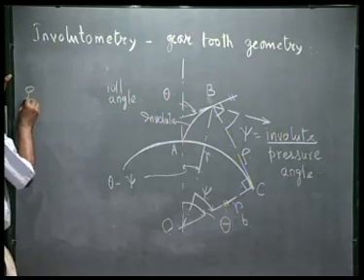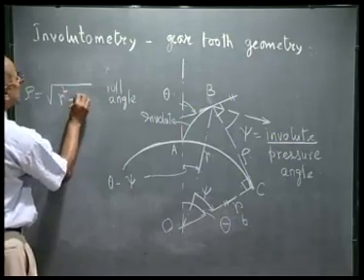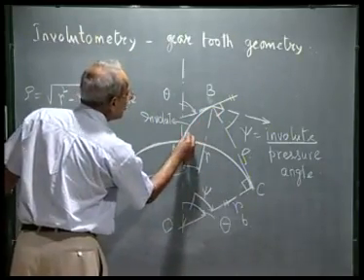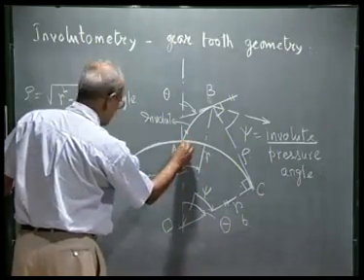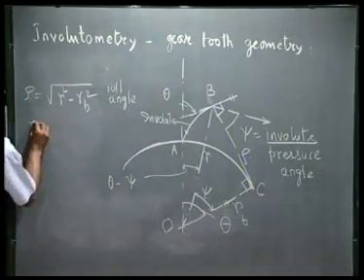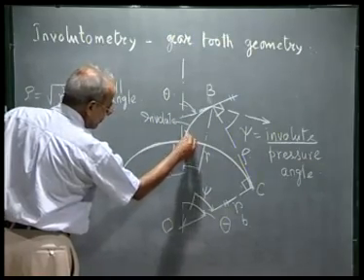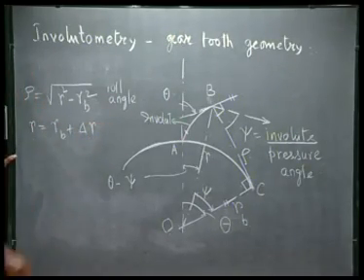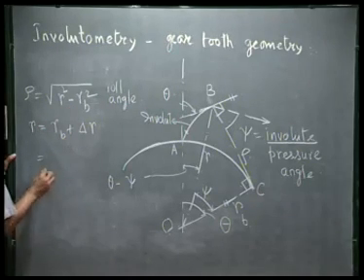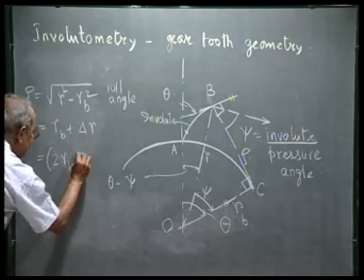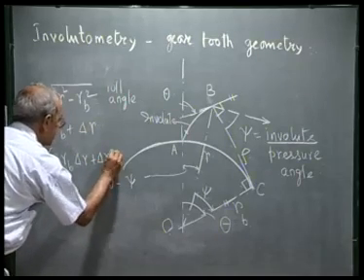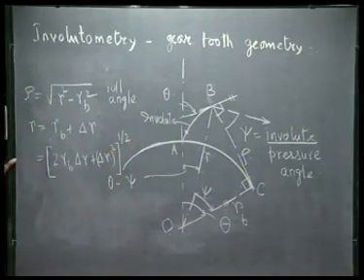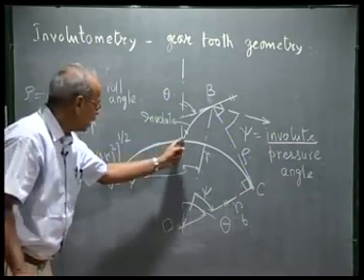We have already got rho equal to square root of r squared minus RB squared, where r is the instantaneous value of this distance. So, if we start from A and go up to some point by changing initial value of r is RB, and then I go to RB plus delta r. Let us say as I start from A, I go a little away from this when r changes from RB to RB plus say some delta r. If I substitute it there, what we get? We get twice RB into delta r plus delta r squared to the power half. This is the value of rho as we go out from this point A.